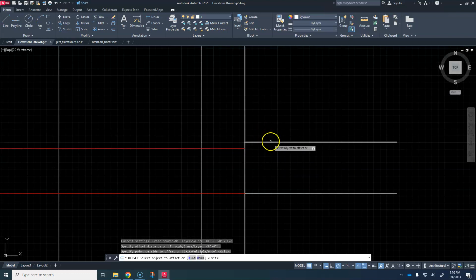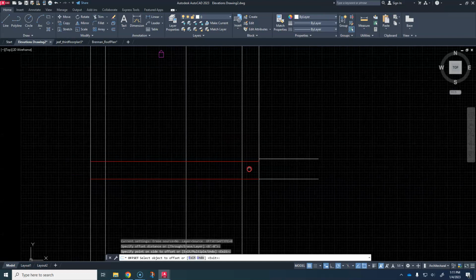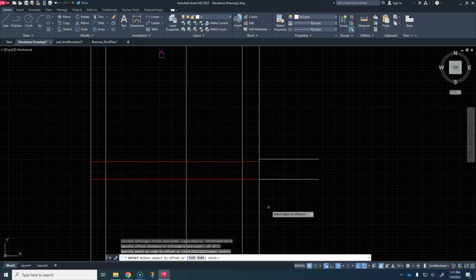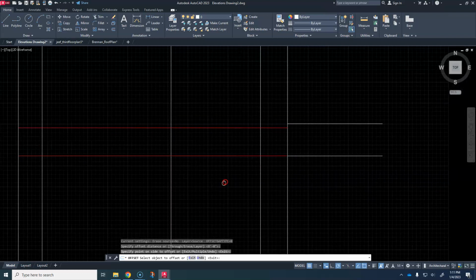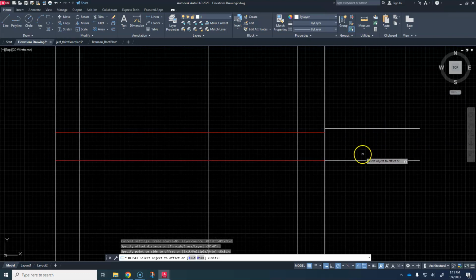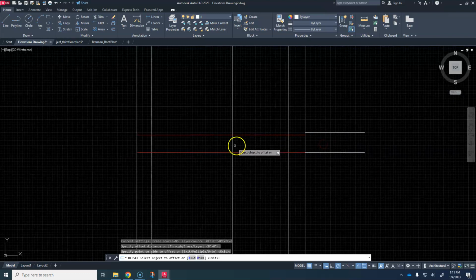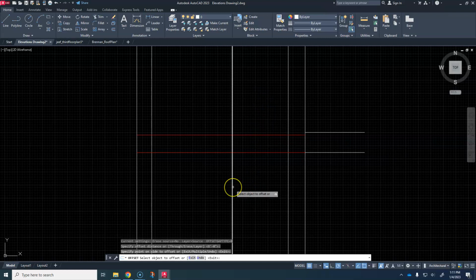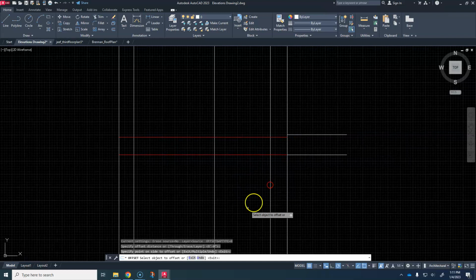And that is going to be our wall level. And you see how that works. Our wall actually goes up some, but the roof overhangs a little bit and hides the actual wall line right here in this type of roof. Some types of roofs do not do that, but in this type of roof, it does. So I just wanted to mark where my floor level is and where my top of wall level is, or my ceiling level, another thing we call that. And then our roof hangs down as it slopes down the front, right here, and that'll make more sense in just a little bit. But anyway, we've got that.